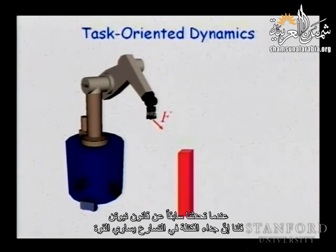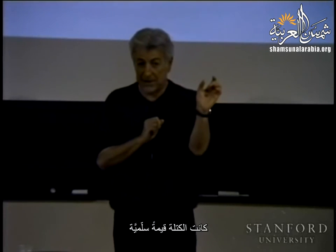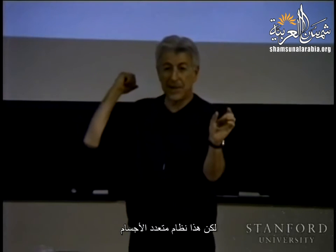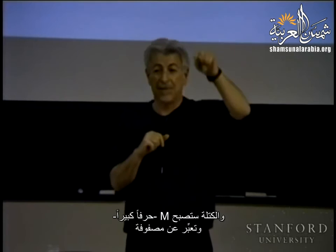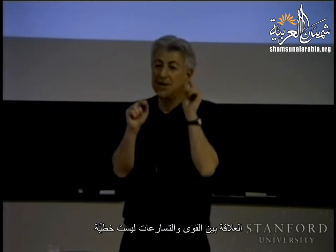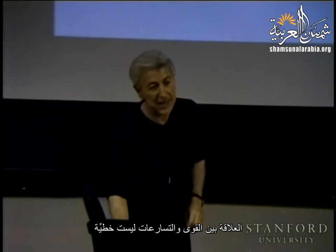Now, when we talked earlier about Newton's law, we said force equals mass times acceleration. And the mass was a scalar. But this is a multi-body system. And the mass is going to be a big M mass matrix. So the relationship between forces and acceleration is not linear.